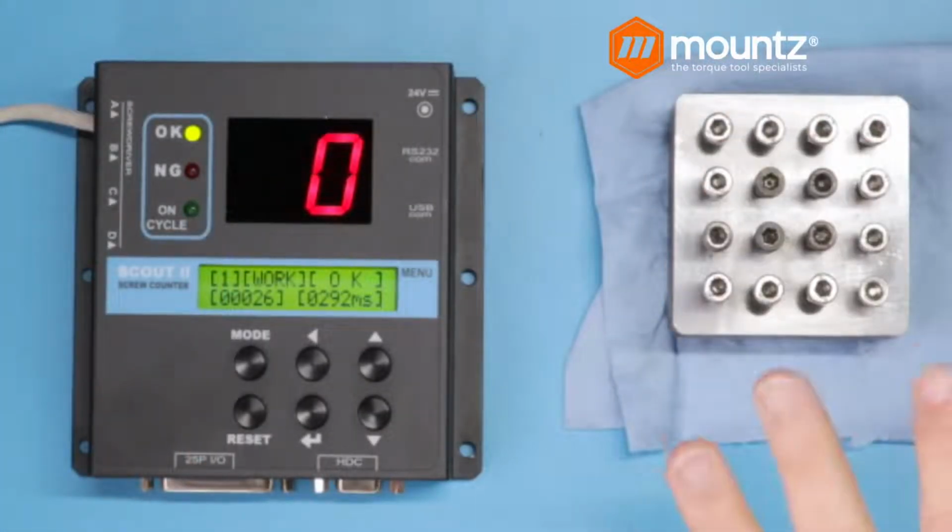All of these fasteners are pulled up to a certain amount of angle, and we'll use those to go ahead and do our testing with this. The system does allow us to do what would be our measuring mode, and it will calculate based off of the number of rundowns that we do. That will allow us to basically automatically program the unit for a specific fastener.